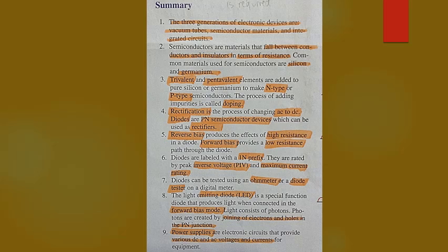The purpose of a transformer in a power supply can be to: 1. Increase the voltage and decrease current. 2. Increase current and decrease voltage. 3. Provide isolation, and/or 4. Provide two equal voltages, 180 degrees out of phase, using a center tap. A rectifier changes AC to DC or pulsating DC.